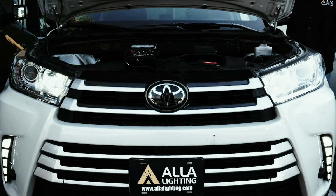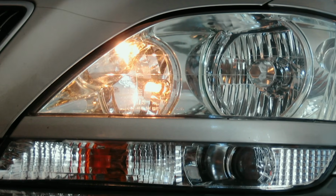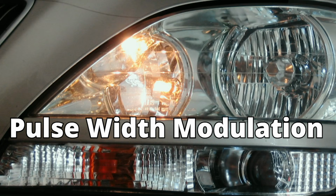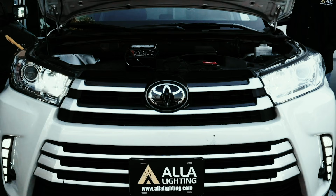For example, this 2018 Toyota Camry LED high beam bulb flickers during DRL mode. The cause is a traditional burning filament is slow to react to the supplied PWM voltage, pulse width modulation, and the change on the burning flame is so slow it cannot even be observed by a human eye. However, LEDs are very sensitive and will flicker under the same DRL PWM voltage.